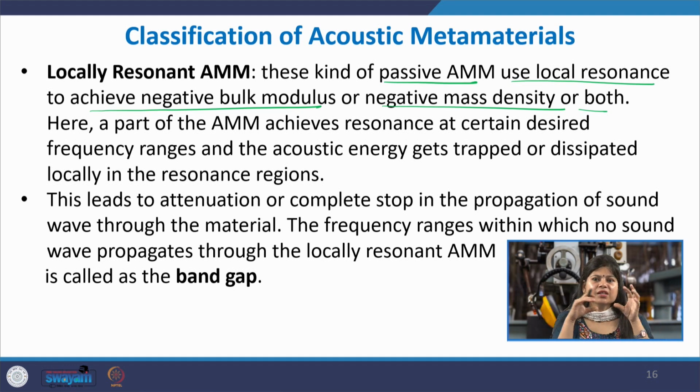Then within that assembly, somewhere locally some element is getting resonating. Okay, so when the sound wave is hitting, maybe a couple of unit cells or a small region within the metamaterial, when the sound wave hits, it sets those unit cells into resonance. So the fundamental frequency of the unit cell matches with the incident frequency of the sound wave, and those unit cells are set into resonance and they start resonating.